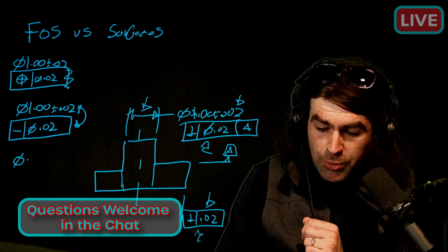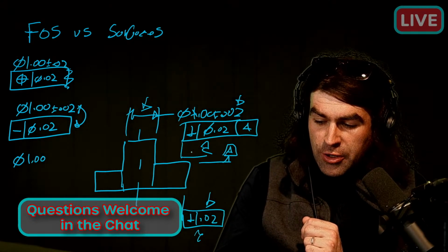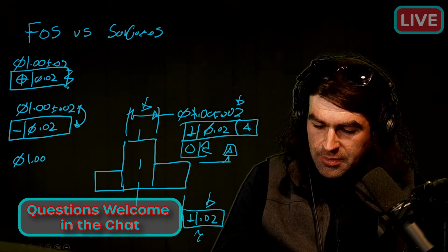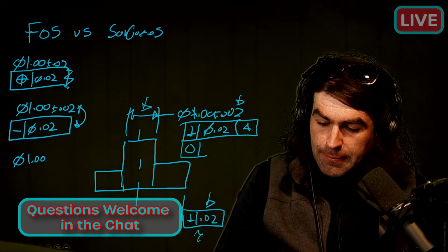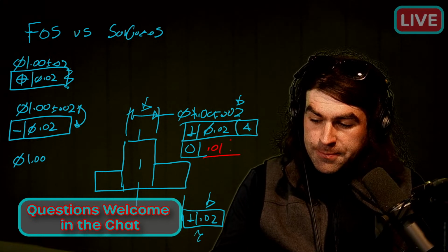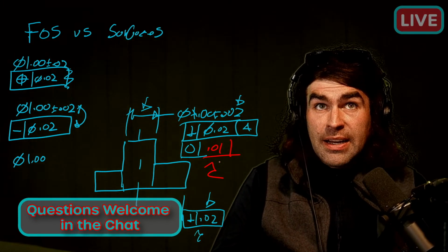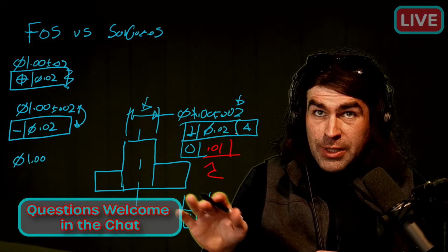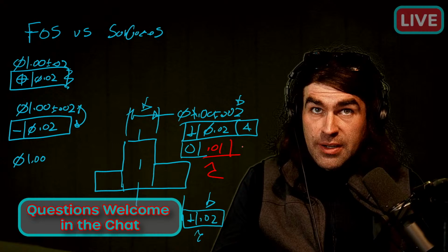Now, I'm pretty sure ASME has outlawed this, where you would have, let me do a little erasing here. So say we wanted to, for whatever reason, apply a circularity to this. I know you'll see this all the time in ISO. And ASME, I forget if it's completely not allowed or if it's just not recommended. I know it's not recommended.